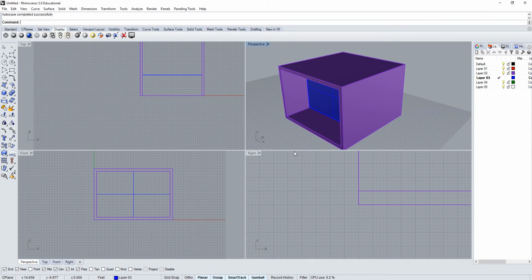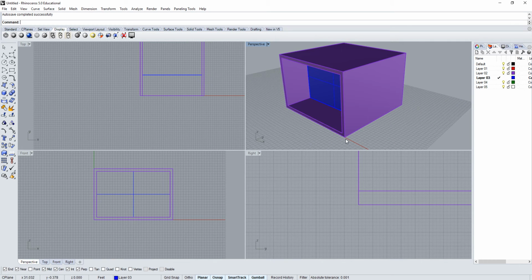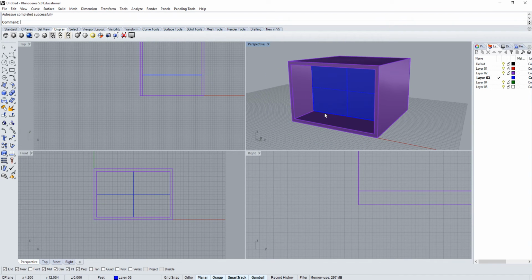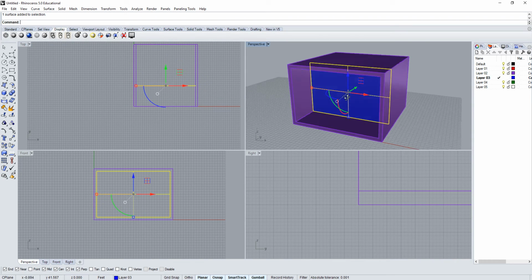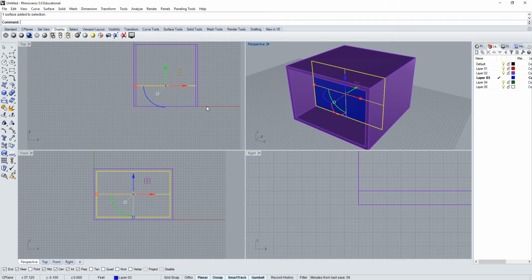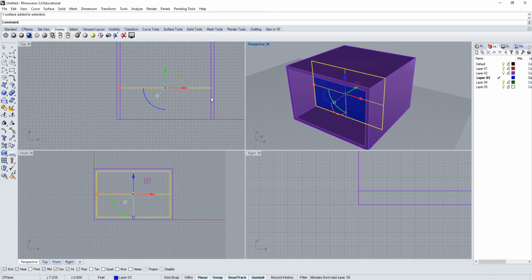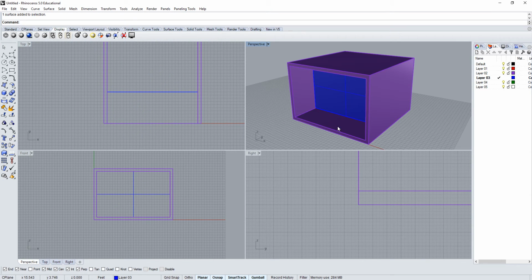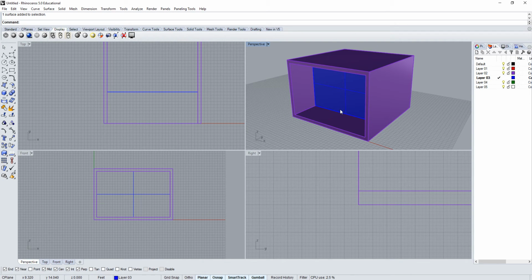It's a simple box. Make it 30 feet wide by 20 feet tall with a 1 foot thick outer surface edge thickness, and then just set the glass back 5 or 10 feet. In fact, 10 feet is probably more accurate, just in terms of having some clearance to see things. What you have here is just a single layer of glass to simulate the idea of a sort of balcony or porch condition. Okay, this is a simulation. It's not meant to be an actual architectural condition. We're just going to start with something that looks like this.